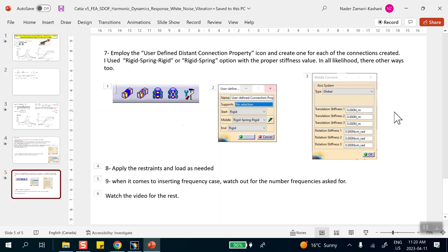And I will show you, in fact, today, if I don't create the beam element, what issues I'm going to run into, which means I have to fix it by going and meshing the beam element. The role of that element is totally irrelevant, but you need it in order to be able to access, for example, restraints and clamps and forces and things like that. Unless you create the beam mesh, you will not be able to access those icons.